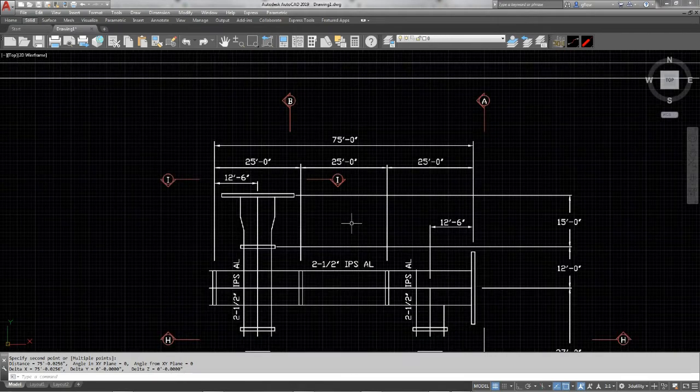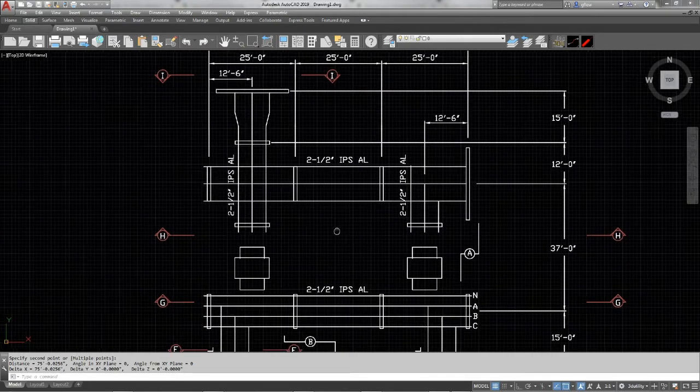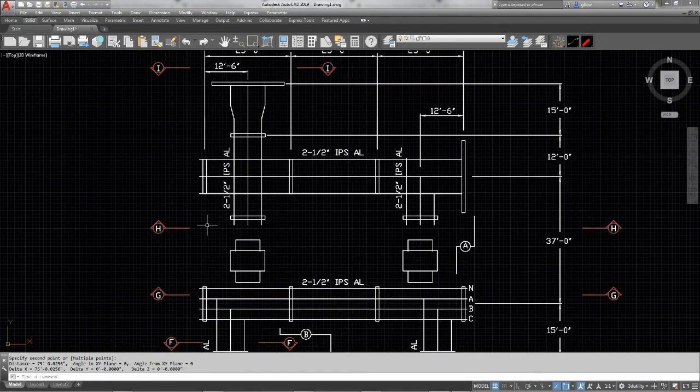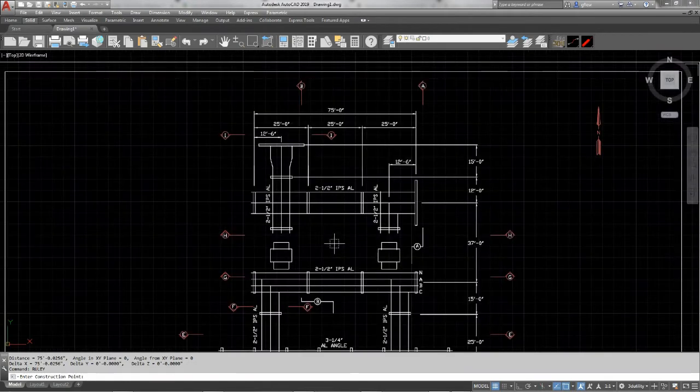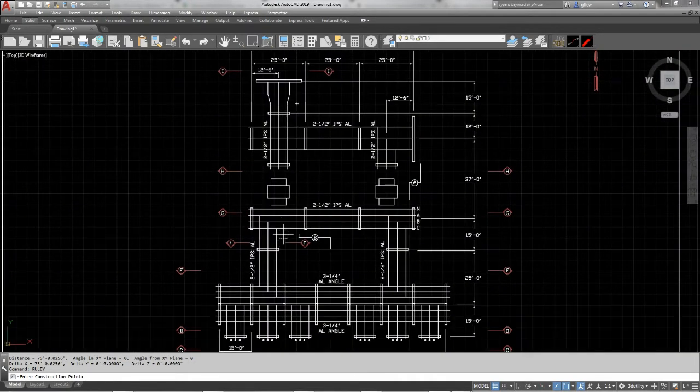Now, the next thing I want to do is create some construction lines that will allow me to locate the various pieces of equipment and the structures, etc., and give me something to snap to, so that I'm not just eyeballing it. And so I'm going to take advantage of the OSNAP properties of the PDF, and also an app that I wrote many years ago called Rule Y. It's a small AutoLISP program, and it will actually draw a line on the Y-axis, wherever I snap, from the top to the bottom so that I get a line fully across the height, in this case, of the drawing.